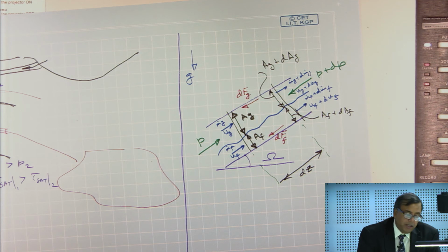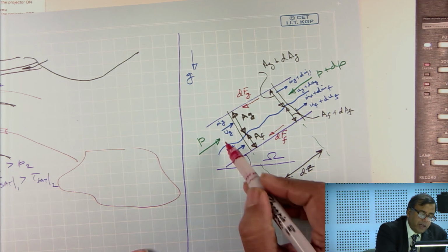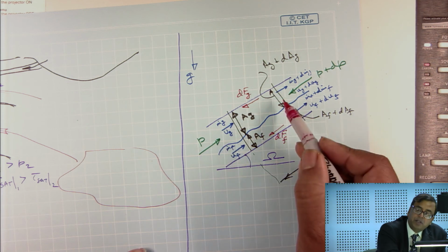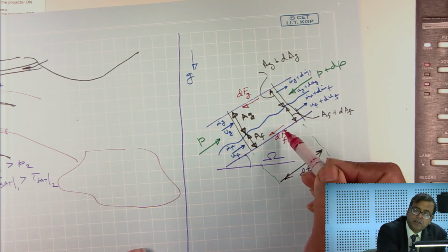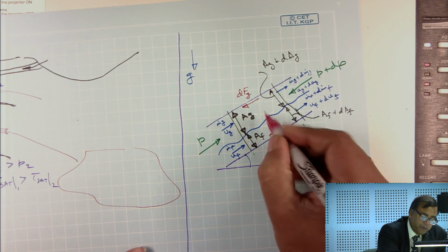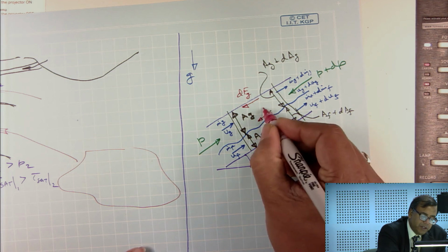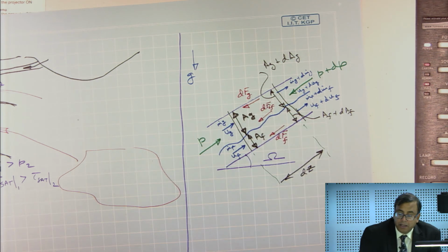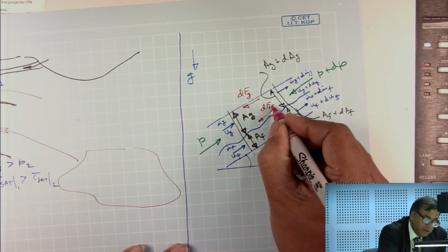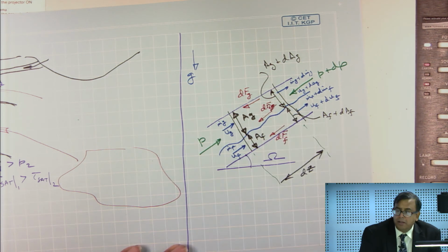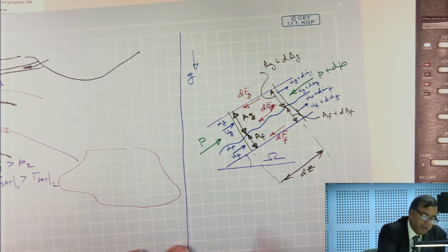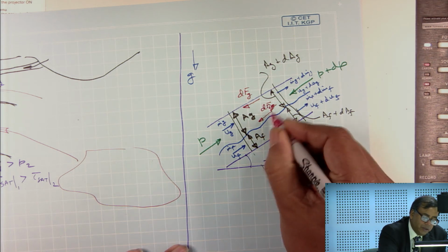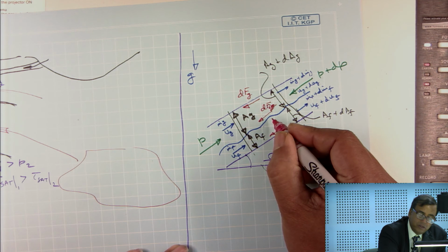There is a shear at the interface. Okay. And so, if I assume that the gas velocity typically is higher than the liquid velocity, then I would assume that there is a force at the interface, let us call it as dF_Ig on the gas side, and then I would have a shear force that has to oppose this shear force, is not it, from the liquid side.